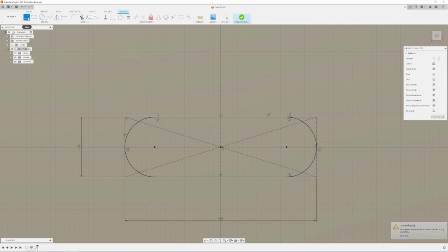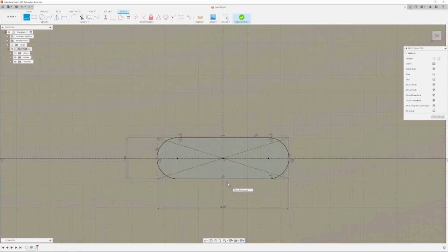Now I need the line tool, which is L, and I'm going to connect that point to that point, and that point to that point. Now notice that that area just kind of shaded blue. That means that that is a totally enclosed area. If I point at it, it just glows a solid blue. So when it's considering a bounded area that is fully enclosed, it ignores the construction lines. That's why I had you do it as construction lines. And then we just have this area here.